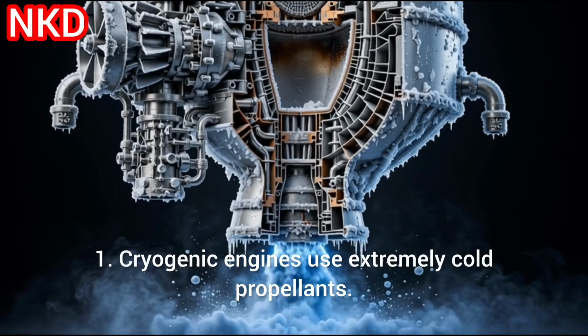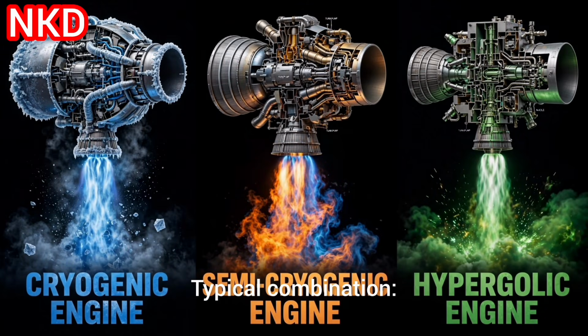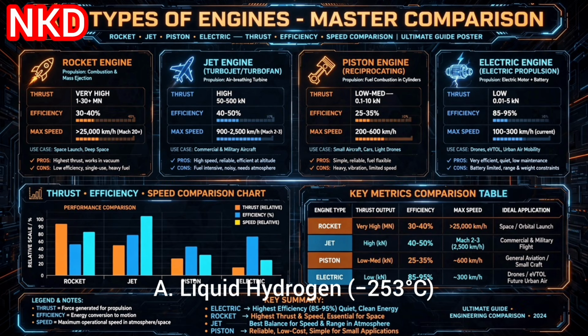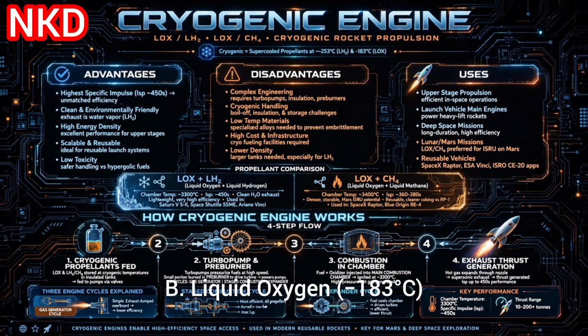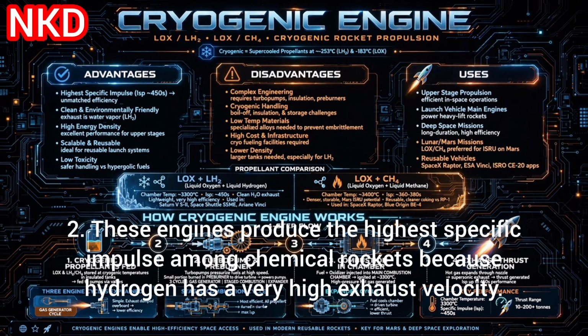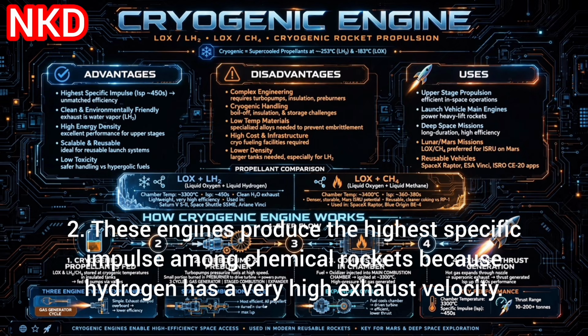We start with D. Cryogenic rocket engines. 1. Cryogenic engines use extremely cold propellants. Typical combination: A. Liquid hydrogen, minus 253 degrees Celsius. B. Liquid oxygen, minus 183 degrees Celsius. 2. These engines produce the highest specific impulse among chemical rockets because hydrogen has a very high exhaust velocity.